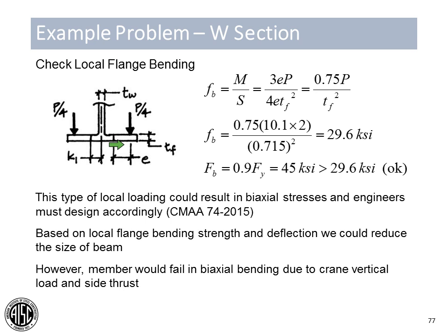Or if you just need a rule of thumb, what I've done in the past is I've taken 2/3 of the distance from the center line of the member to the toe of the flange and use that as my load application location. But in balanced loading like we have here, that eccentricity actually factors itself out quite nicely, so you can actually apply it anywhere you want on the member.